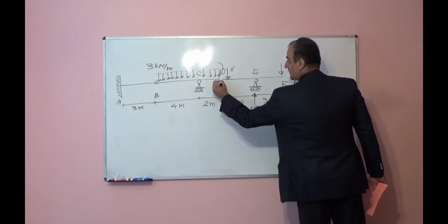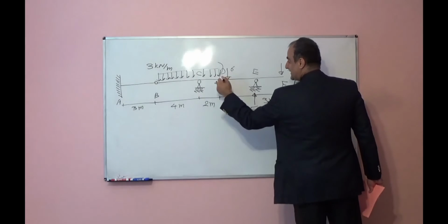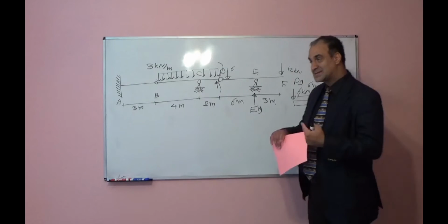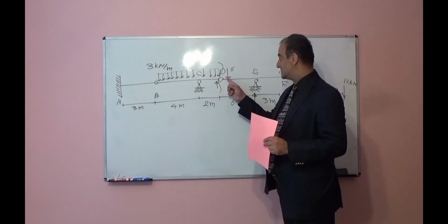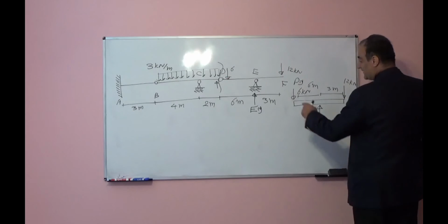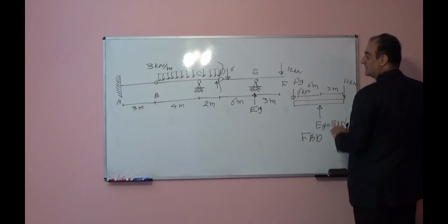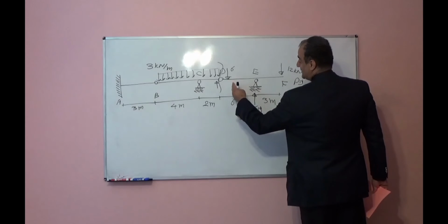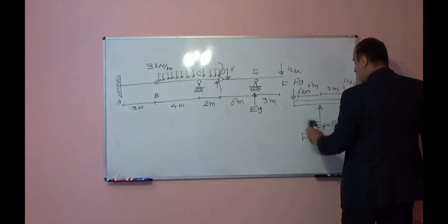So Dy for the other side should be upward, because if we attach them together, downward and upward, they cancel each other. We will get 0. We will have the continuous structure. So now I find in this free body diagram Dy downward, so the action of the left side to the right side will be upward.